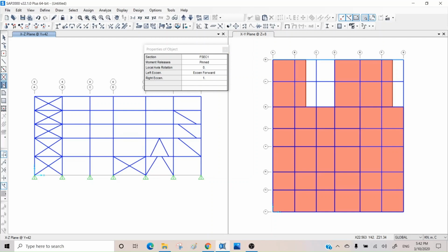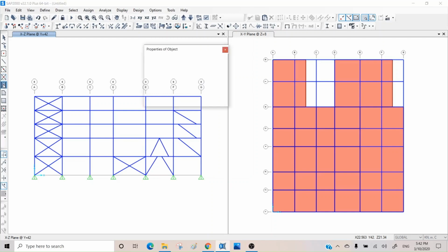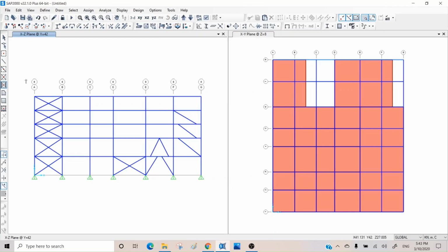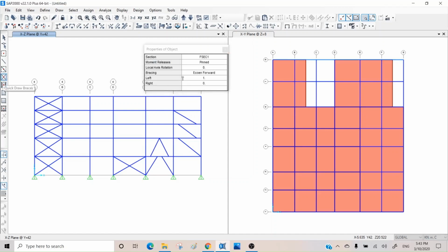If you come here and press this secondary beam options, just press it because it gives you the right arrangement and options for drawings, then close it. Don't do anything. Again, when you come back here, you can see the options correctly. So just bear with it until it actually gets fixed.